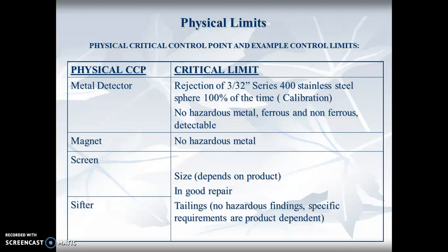Screen, you could have that depending upon the product. If we're making a slurry, like a hot dog, we could see that a screen would be present to see if there were any larger pieces, and that would catch them. But you have to make sure that your screen is in good repair.